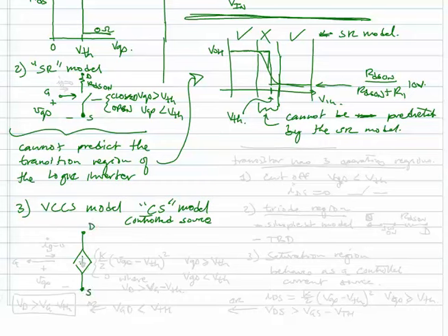Okay, we still have our controlling signal from the gate. It doesn't really go anywhere. That's one of the things about the MOSFET, is that there's no current that flows into the gate. Never any current that flows in the gate, so it's always equal to 0. But the voltage is important. The voltage is what controls it. So we have VGS here.